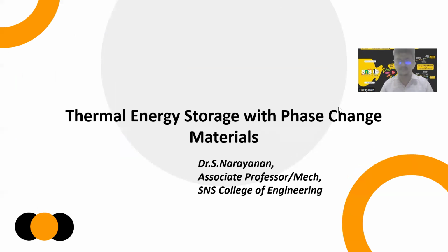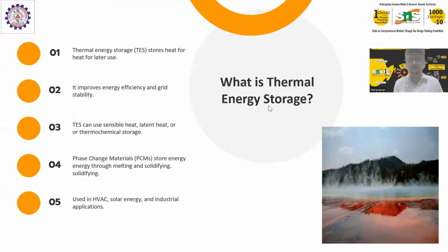So thermal energy storage with phase change materials. So what is thermal energy storage? Thermal energy storage is nothing but storing the heat for later use. So you have dynamic systems where energy is produced and utilized, or energy is utilized as it is produced. So these thermal energy storage systems store heat for later use, right? Such storage will improve the energy efficiency of the overall system and grid stability. So thermal energy systems can use sensible heat, latent heat, or thermochemical storage.